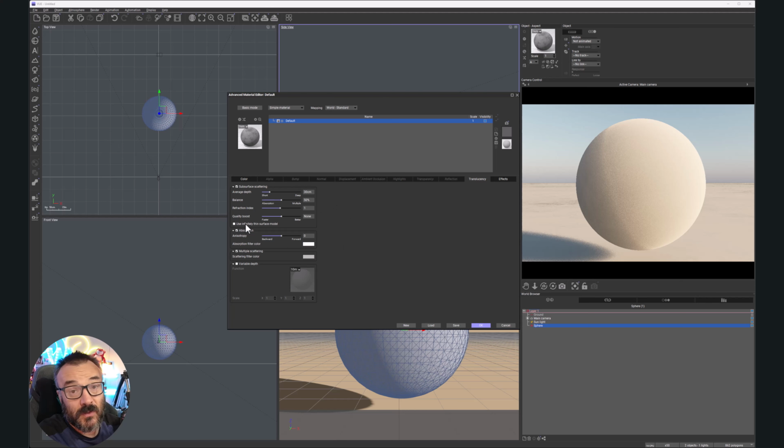And as I said before, in some cases, it's much easier. Like right here, we have a quality boost. And what the quality boost actually does is perform two options in this case. One, it increases how many times rays can bounce and calculate. And second, it increases anti-aliasing. And anti-aliasing will analyze the area around those elements and try to smooth them, creating a little bit better gradients between contrast points. Well, it's a little bit more complex in the back end, but in a simple way that's actually what's happening here. And you can notice as we go, it will be a little bit better.